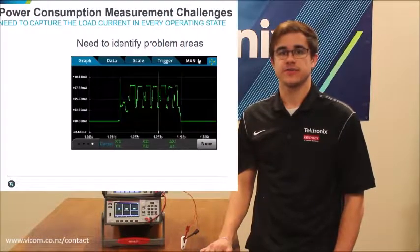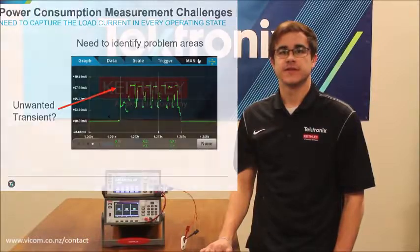Because the 7510 has a sample rate of up to 1 million samples per second, a very clear and detailed waveform can be found, exposing the current profile and allowing you to identify any power wasting problem areas such as unwanted transients. The large dynamic range and the high sample rate, coupled with an internal buffer capable of storing 27.5 million readings, make the 7510 the ideal instrument for characterizing average current of an IoT device, and doing so over the duration of a typical use case.